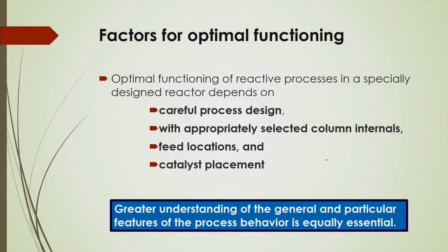Factors for optimal functioning. Now, optimal functioning of the reactive process that you have to consider for reactor design will depend on careful process design with appropriately selected column internals, feed locations and catalyst placement. Very interesting, whenever you are designing any reactor, you have to consider the process design in such a way that internals are required or not, because your process intensification will be based on mixing of the reactants.